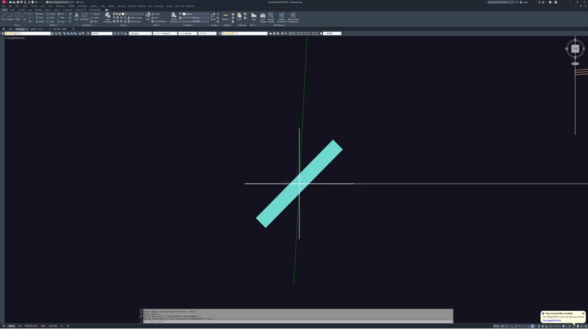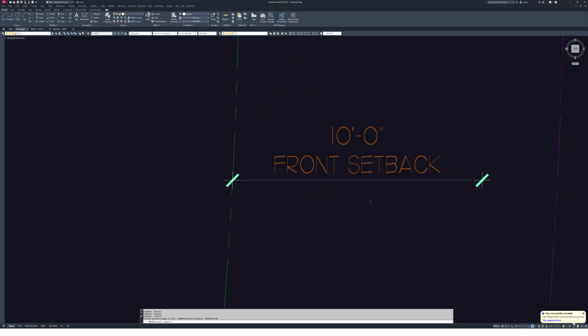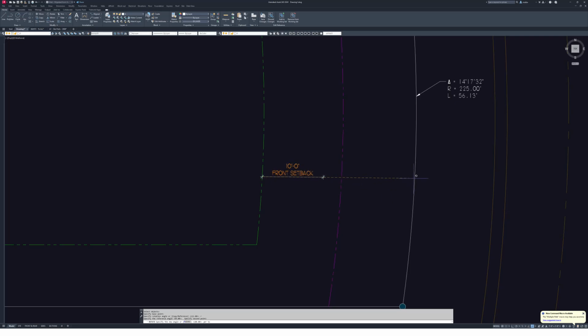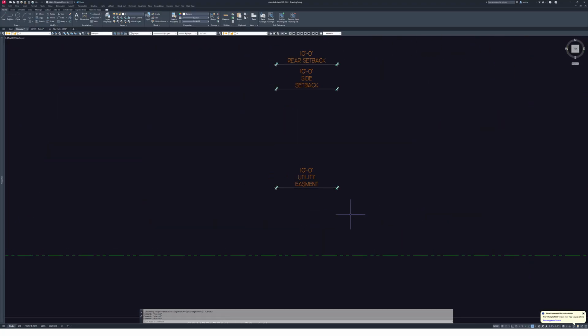It connected those two as a dot, and then we're going to rotate and give a reference to this point, come out anywhere, go here, and then I'm going to do PER for perpendicular, and it rotated just enough to make it tangent to this angle. Now you can see it gives me a perfect 25-foot setback.